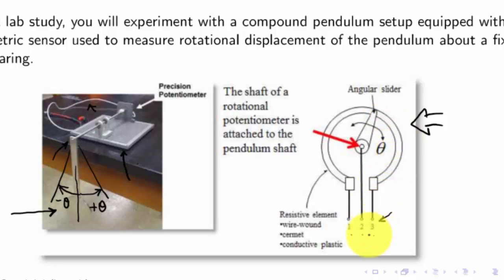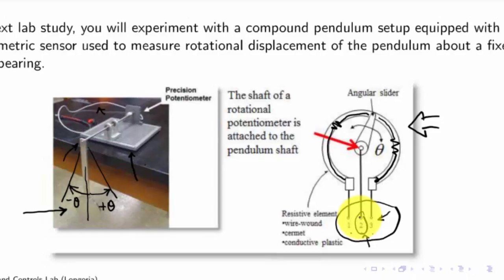For example, between terminal 2 and 3, you're forming a resistor, say here to there, and another resistor here to there. So you can see how the two resistors vary, and what you do then is connect these three terminals to power, ground, and then we'll usually pick off the signal from the middle terminal. We'll look at this circuit in the next slide.